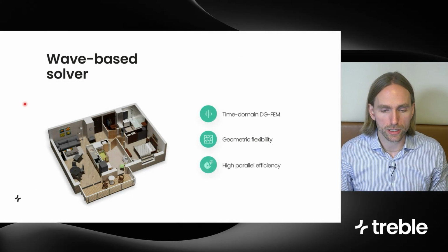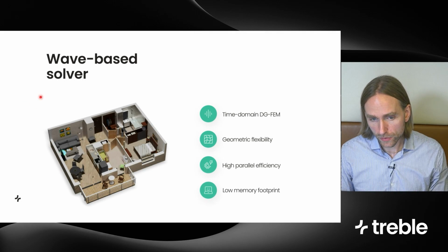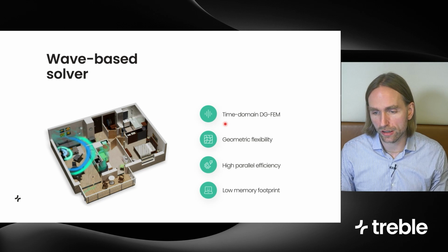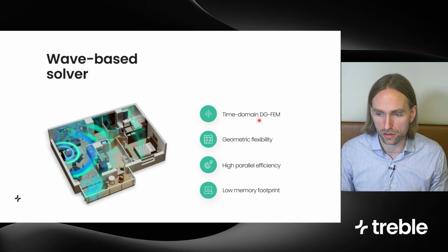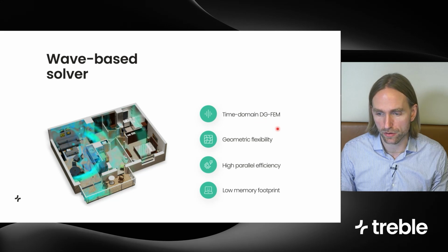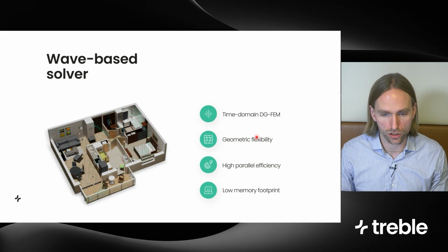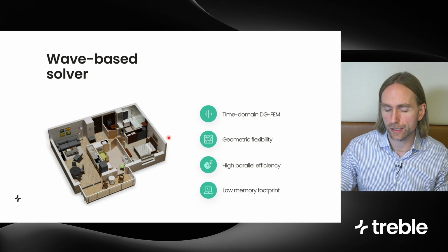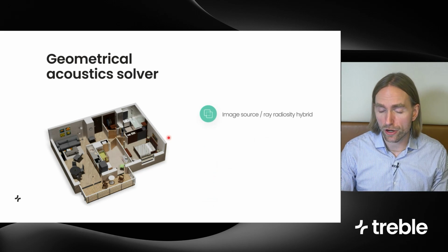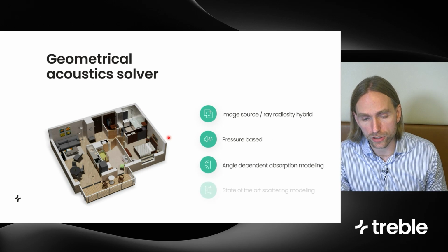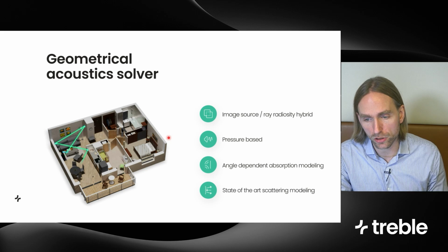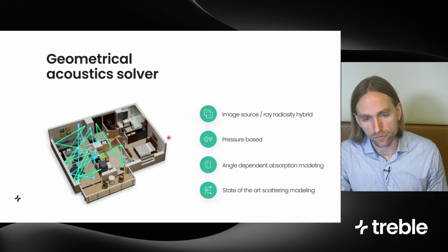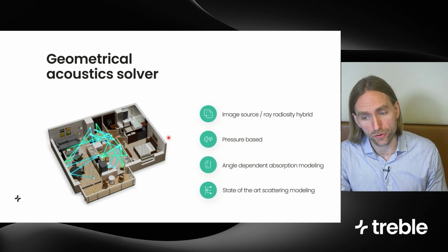A few words about each solver. The wave-based algorithm is using a finite element flavor called the discontinuous Galerkin finite element method, very suited for complex geometries and high parallel efficiency. We're also very proud of our geometrical acoustics solver, which is a state-of-the-art high-frequency modeler, combining phased image source methods and ray radiosity methods.